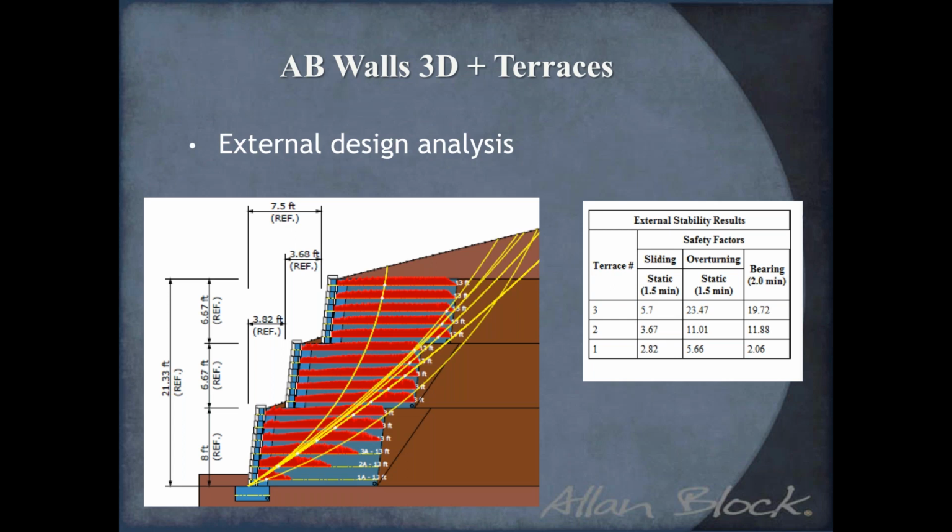But for every terrace, we're looking at the sliding, overturning, and bearing safety factors and how they relate to each other as surcharges or so forth. So pretty standard external stability calcs will continue into the terrace section.